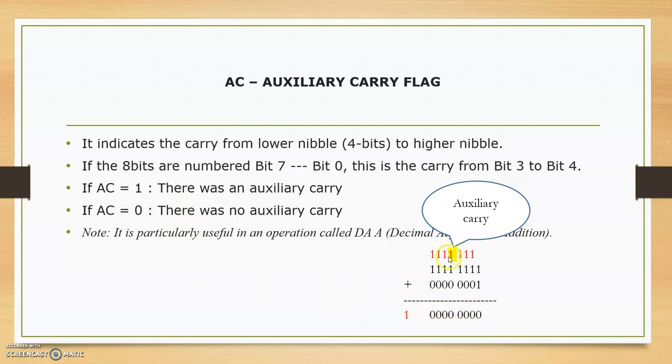This auxiliary carry is not taken into consideration in all situations. It will be considered when we are doing decimal adjust just after addition, that is, when the DAA instruction comes. In all other cases, only the carry out of the MSB is taken into consideration.